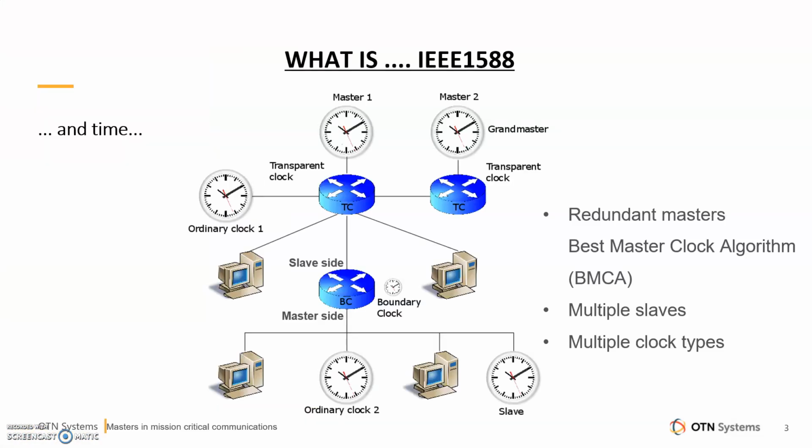So 1588 is all about synchronizing clocks between grandmaster clocks, or high precision clocks that could be in a critical location like your control center, backup control center, or other critical location where you'd invest a great deal of money on a high precision clock. And then you'd want to synchronize boundary clocks, maybe inside your critical substation, or maybe eventually in all of your substations. And ultimately, the boundary clock acts as a master for ordinary clocks distributed inside your substation and every device